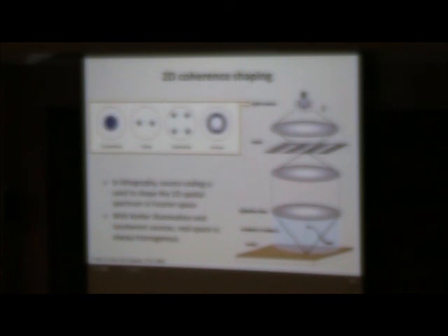So moving to more fancy lithography, it puts in different sources that are not just a circle of different widths, but actually dipoles and quadrupoles. Dipoles if you want to print lines, so it's good to have things coming in two directions. This is basically two-dimensional patterning within this four-dimensional space. It's in the Fourier plane, so everything you do here is going to affect every point here. At the object or mask plane, the illumination's homogeneous everywhere. It just has different directions of propagation. So, 2D patterning of 4D.